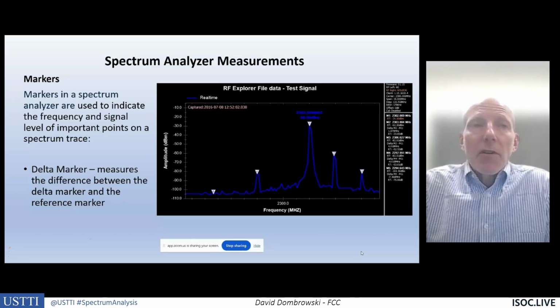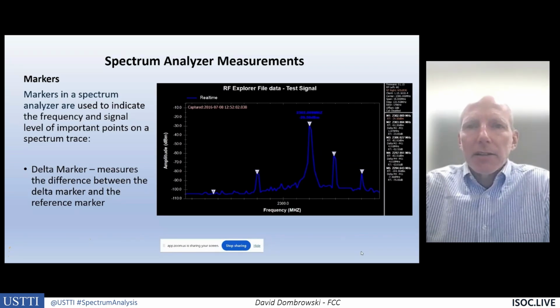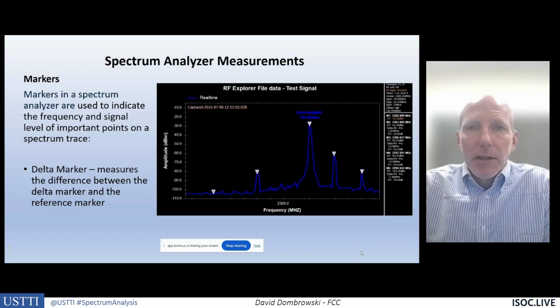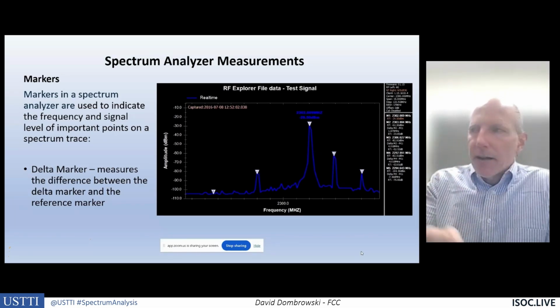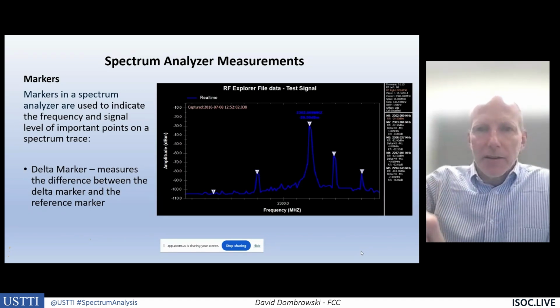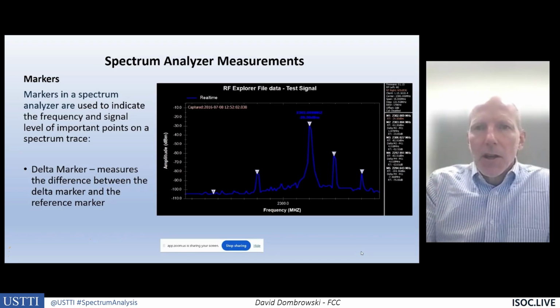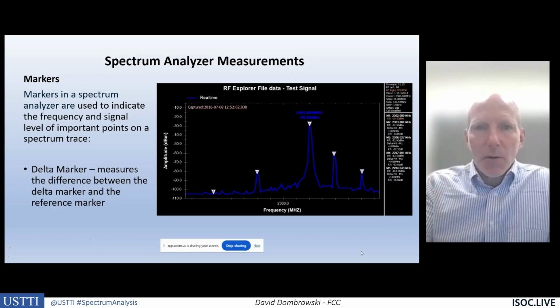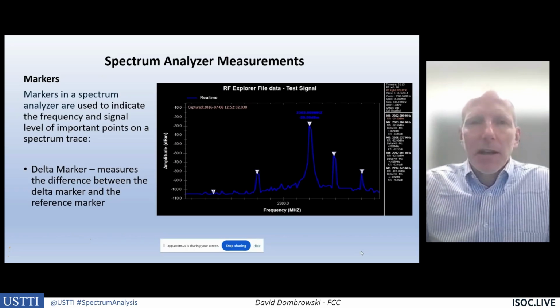Okay, so yes, you can create your own interference. There was a presentation earlier in the week on interference, and I'm sure Shannon Gunter covered this, but we talked about intermodulation. When we put multiple high-powered antennas next to each other, you can have intermodulation. If I have an antenna and another transmitter nearby, the signal from that other transmitter can come down to my antenna into my receiver. Because it's so strong, it overdrives my receiver and creates intermodulation. And so that will increase my noise floor and decrease my sensitivity, just like we explained in the spectrum analyzer.